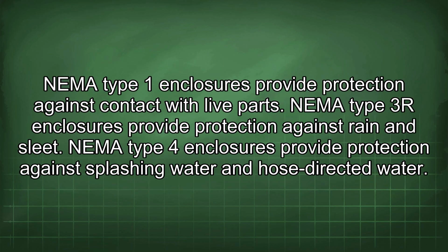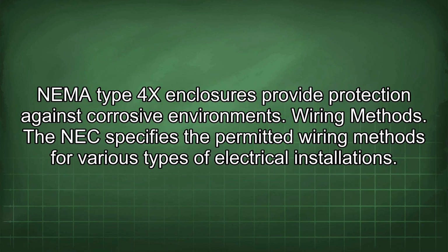NEC Type 1 enclosures provide protection against contact with live parts. NEC Type 3R enclosures provide protection against rain and sleet. NEC Type 4 enclosures provide protection against splashing water and hose-directed water. NEC Type 4X enclosures provide protection against corrosive environments.